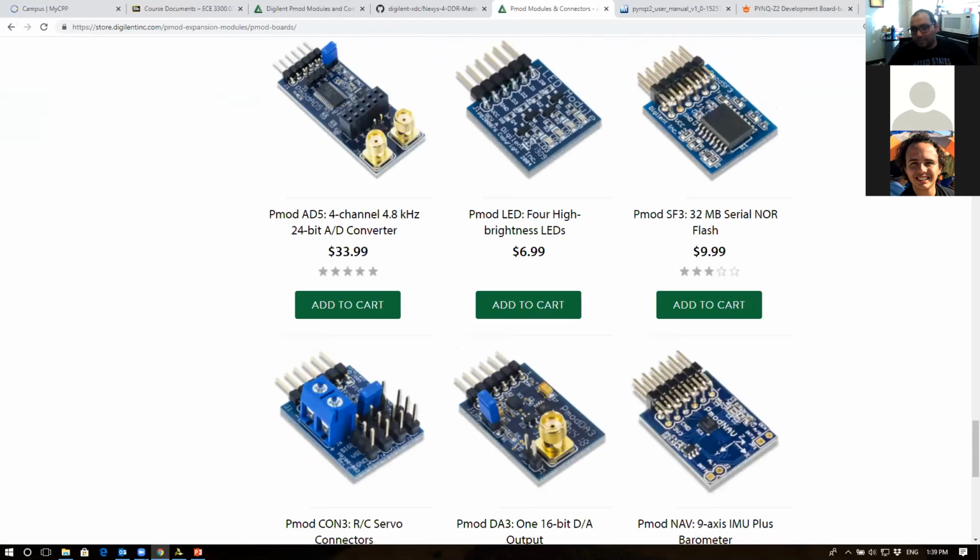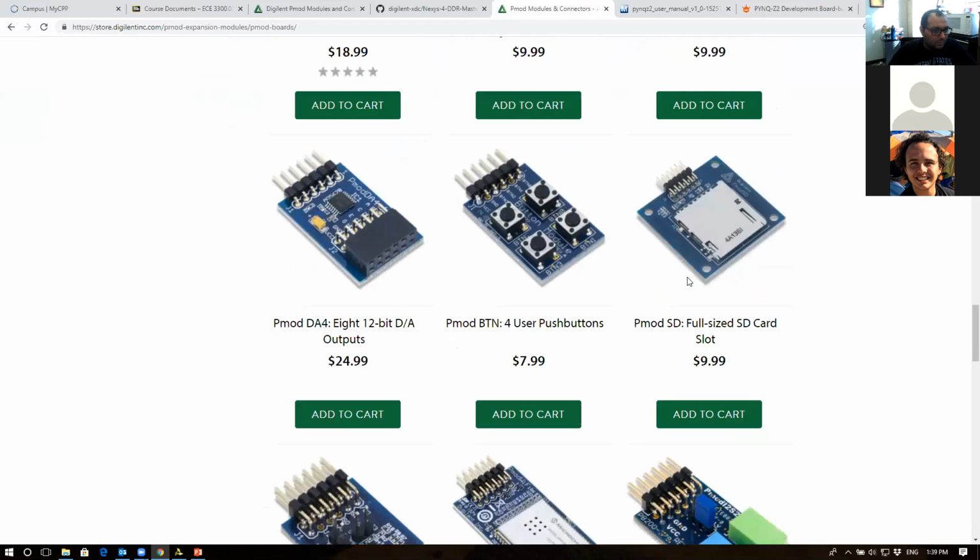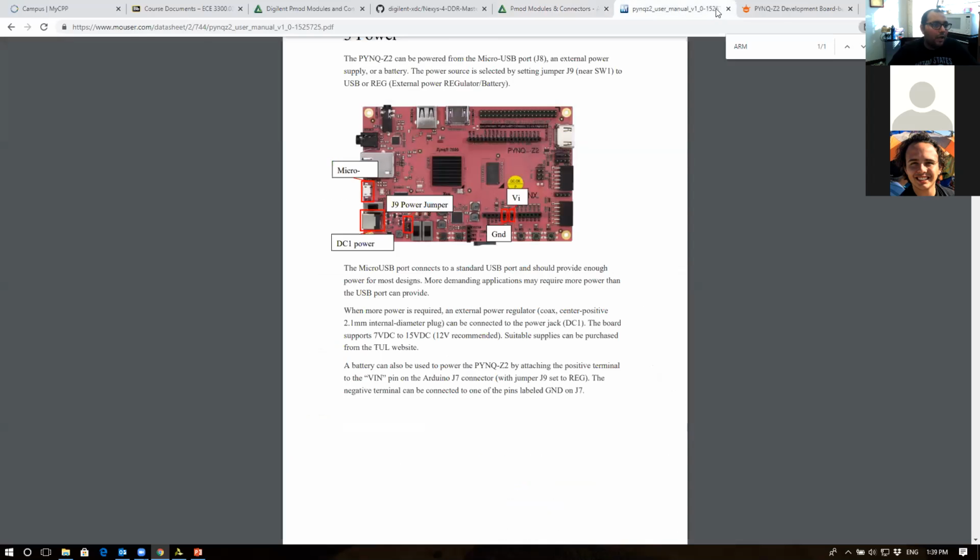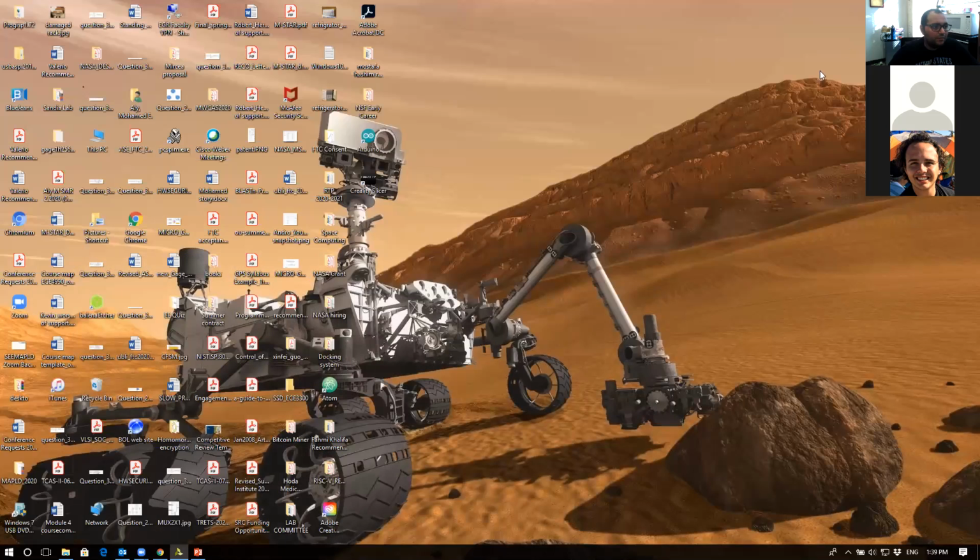Is the ARM processor the same as the soft processor on the FPGA? For example, is the MicroBlaze an ARM processor? No. MicroBlaze is using fabric. Someone asked, isn't the board capable of running Python? Yes, it ran Python. So the MicroBlaze and the Zynq aren't ARM processors? They're soft processors, right? That's the correct term. MicroBlaze is a soft processor. ARM is an ASIC processor. It's like a fixed processor on a chip.